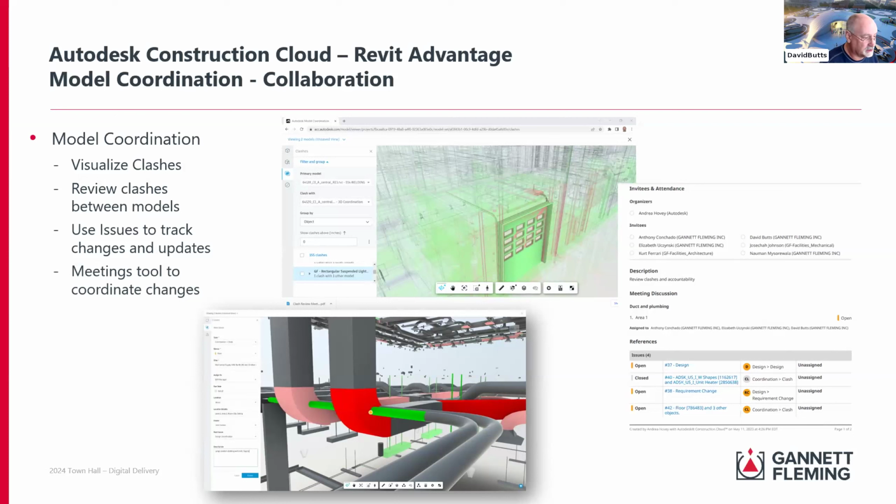And so if you take a look at the lower image, this is actually a shaded view showing a pipe going through a duct. And so all that highlighted duct is something that was reported as a clash with the coordination tool. And so now you can also have meetings and use the issues tools to actually track what's going on with these conflicts and resolve them within one environment.